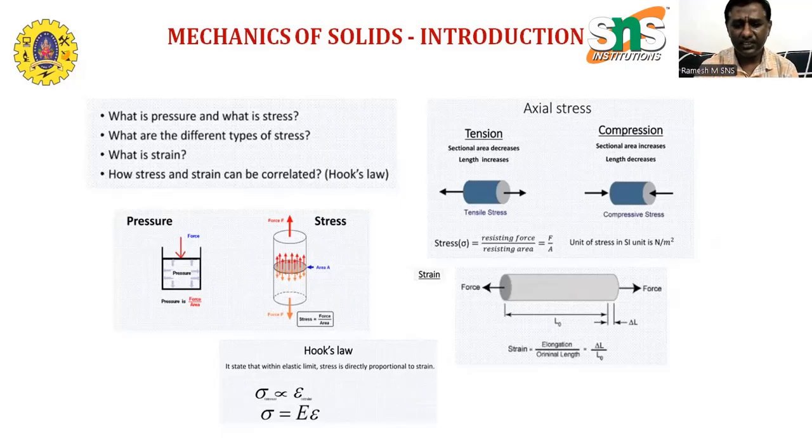And what are the different types of loads in beams? Generally we have static load, dynamic load, impact load, thermal load, point load, and distributed load. But in beams, we generally use the point load as well as the distributed load. In distributed, we have uniformly distributed and uniformly varying load also.